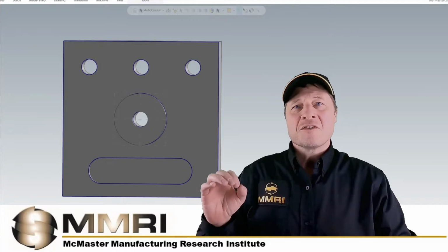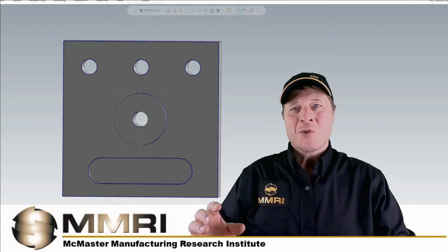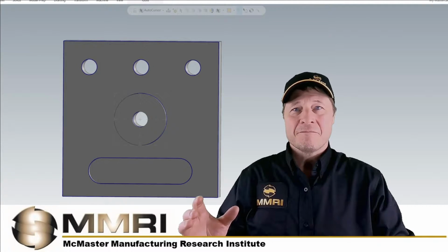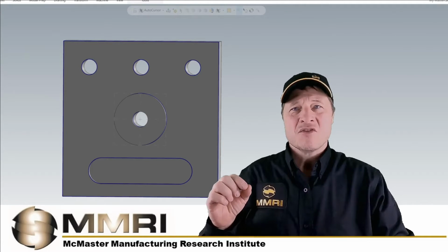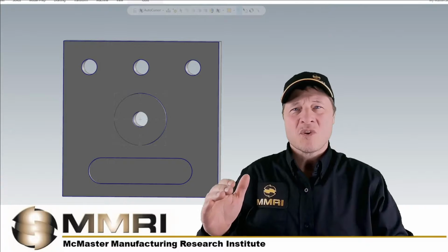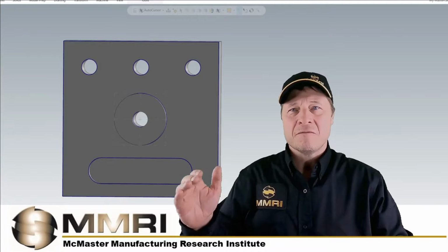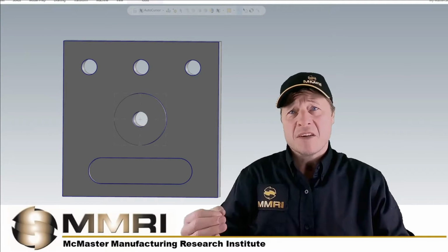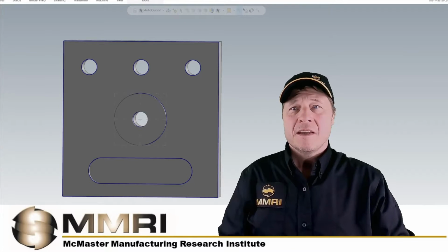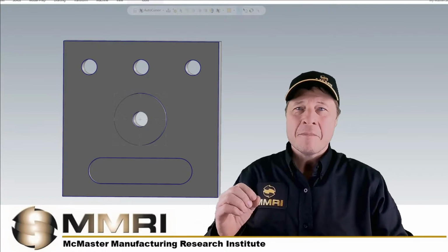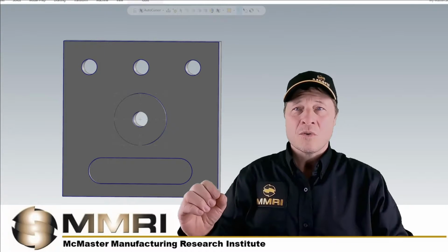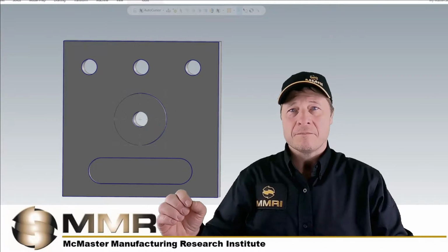One of the first things we need to know regarding drawing standards is how to look at a print. A three-dimensional part needs to be described by way of different views on a two-dimensional plane. Therefore, a three-dimensional object or part is described by a method called orthographic projection.